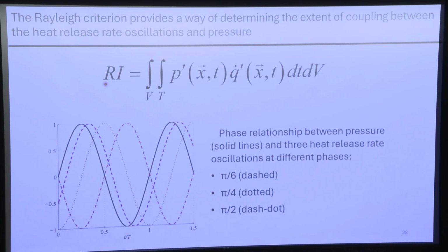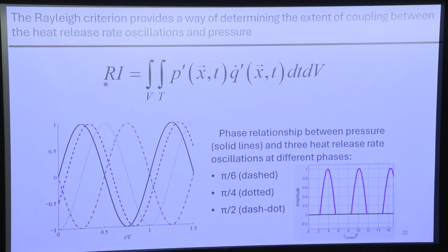So what this tells you then is the name of the game thermoacoustically is the phase. So I took this figure from a tutorial I teach with Tim Lieuwen at Turbo Expo. Basically, you could ignore what this is; we'll talk about this in just a second. Assume that the x-axis is the phase, but not wrapped, right? If you wrap a phase, you go from 0 to 2 pi, and then you start again 0 to 2 pi. Let's just keep counting, right? 360, and then 720, and then just keep going, right? And so there are these regions